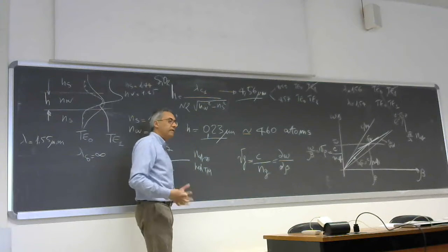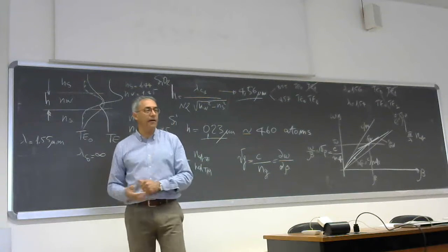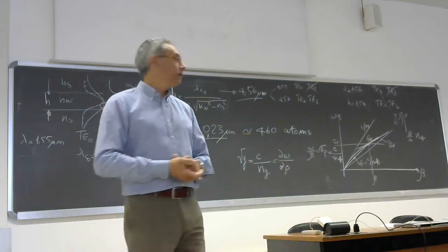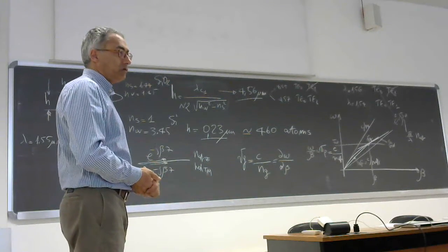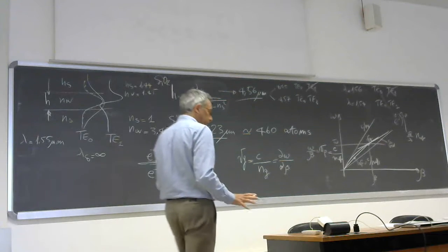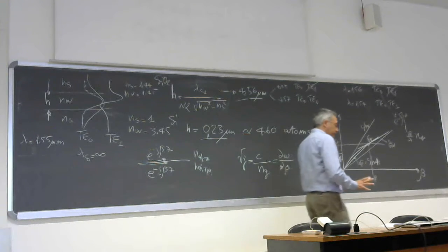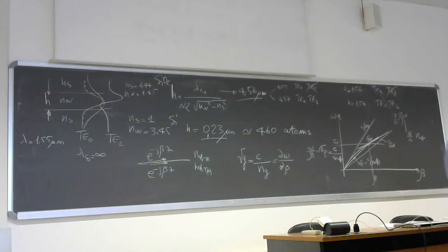We have a group index for the TE and a group index for the TM. We have an attenuation for the TE and for the TM, etc. So everything is double. The cutoff frequency of the two solutions is very similar, and whether the behavior is similar or not depends on the technology, on the shape of the waveguide, and the refractive index.